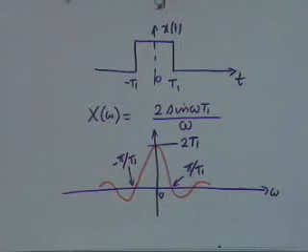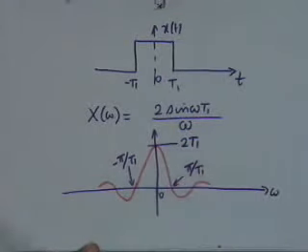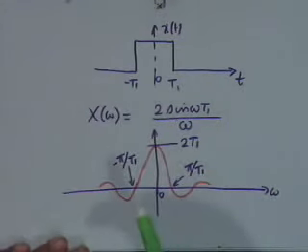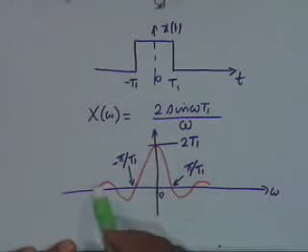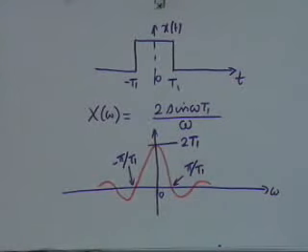Now the question that I ask now is the following. Exactly like Fourier series, which contains an infinite number of terms, k equal to minus infinity to plus infinity for a periodic function, if I wish to reconstruct x of t from the spectrum, obviously what I have to do is to take the infinite spectrum from minus infinity to plus infinity. In the case of Fourier series, it was a line spectrum. In this case, this is a continuous spectrum. I have to take the spectrum and take its inverse Fourier transform.